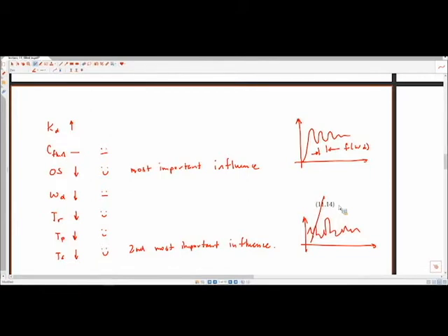What MATLAB and Simulink is doing is they're actually using a filtered derivative, so it has an extra parameter. We'll talk about what a filtered derivative looks like later, but they're basically filtering the signal and taking the derivative of it, and they're making the cutoff of that filter so high that it doesn't really affect the main response, but it cuts out noise. So there are many ways around that problem, but if you just apply a really strong derivative without a filter, it could cause problems.